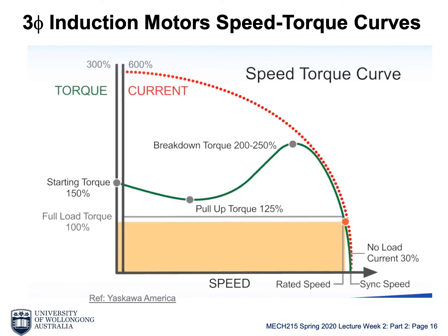There are two things to consider when it speeds up. Firstly, the motor torque always needs to be larger than the required torque. Secondly, the starting process should not take too long. If it takes too long, because the current through the motor at startup is very large, the motor is going to overheat.